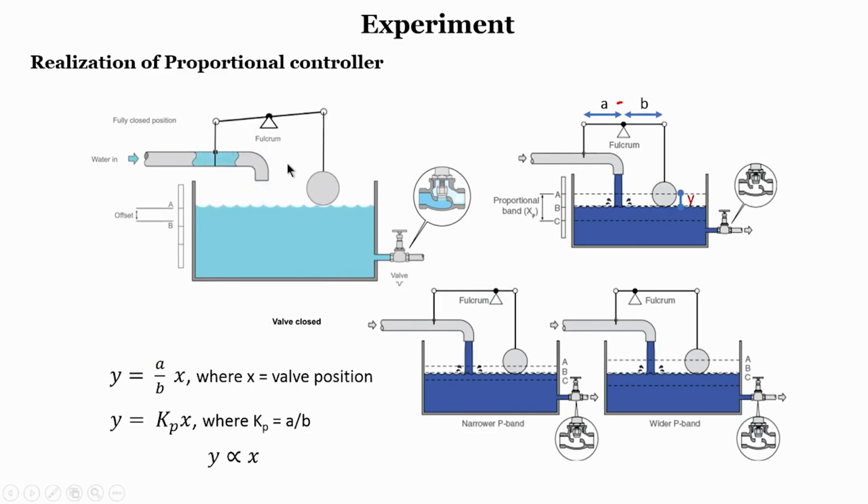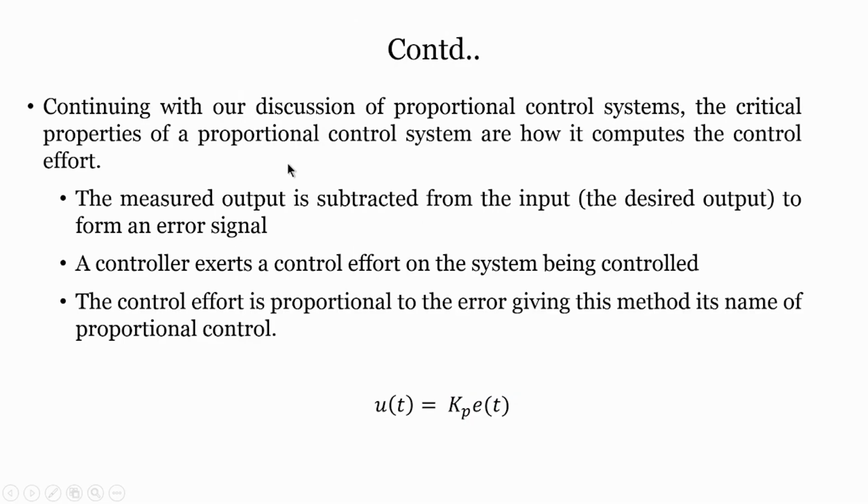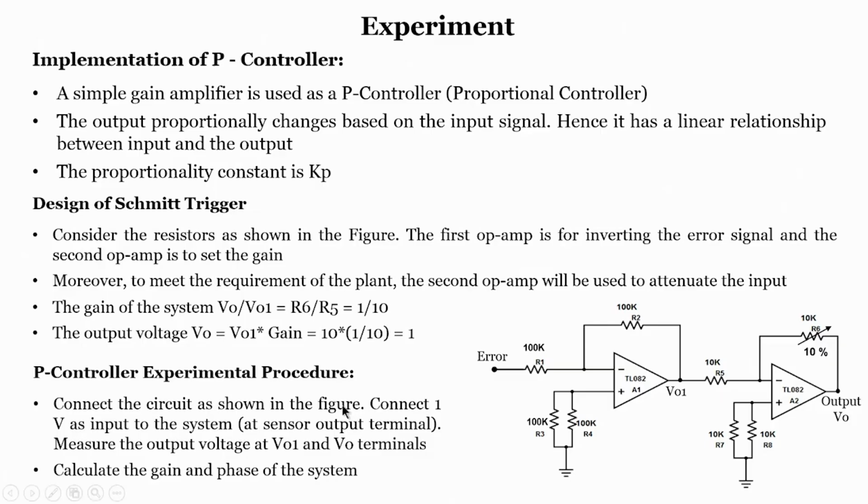the electrical way. So, when we recall the input to the plant, the input to the system, the controller input is nothing but the error signal, which is the difference between your set point, the desired output, and the actual output. That difference input is connected to the Kp. If the error is higher, a higher input will be given to the plant. If the error is smaller, a smaller input voltage will be given to the plant. So that means we require a simple gain amplifier. If you see, this is a simple gain amplifier that we are using.